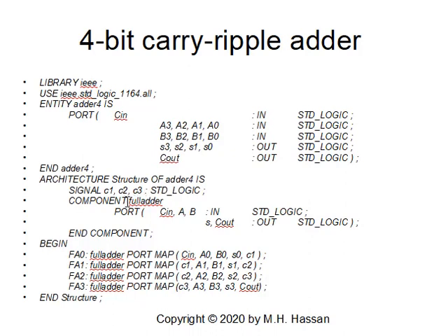Now, I declare the full adder as a component, and I will add component. When I define it as a component, the port definition of this component has to be identical to the entity full adder when we declared it as entity full adder in another program. Once I declare it as component, I will end component. Once I declare it as component, I can use it in a port map statement. So I will say full adder, FA0, full adder port map.